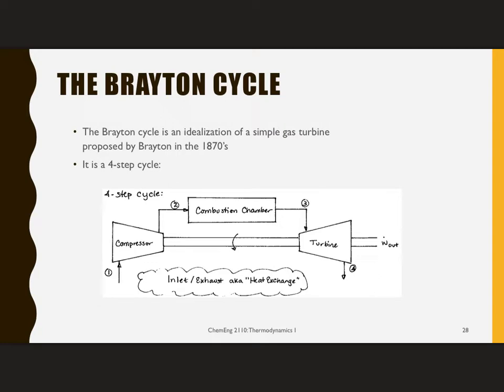We're going to start by bringing in air from the surroundings. Again, if you're thinking about a jet engine, what that would do, right? It's going to bring air into the device, and it's going to compress that air to a high pressure. It's then going to heat that air up, and the way it's going to do that, right, we're not going to be able to boil it, right? That makes no sense. It's already a gas. And so we're going to run it through a combustion chamber that's going to provide a lot of heat and add that to this. So the air is actually going to be part of that combustion process. We add fuel, a spark, and you've got yourself a fire.